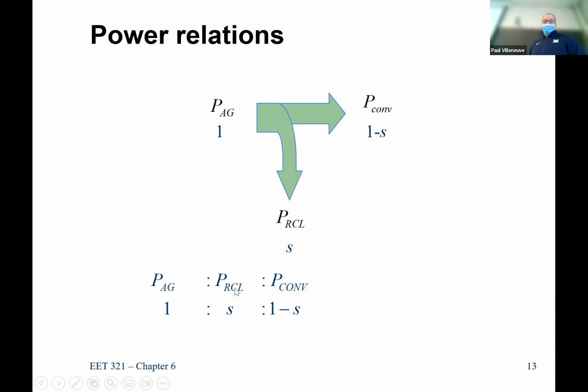Variable frequency drives, our mechanical engineering friends will say, let's run a 9.3 horsepower load. We'll run it with a 10 horsepower motor. It's going to run at a higher speed, but that pump that it's driving doesn't need more than 9.3 horsepower. So they have to design a recirc line. Well, if I could run a variable frequency drive that essentially changes the sync speed, so it's going to adjust its speed, so it's going to reduce the slip. So not only does a variable frequency drive mean you don't have to build a mechanical system that takes all that excess energy, but it also means you're going to run at a higher, more efficient motor operation because you're going to run at lower levels of slip.